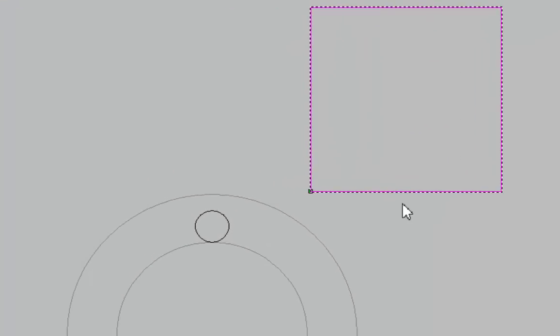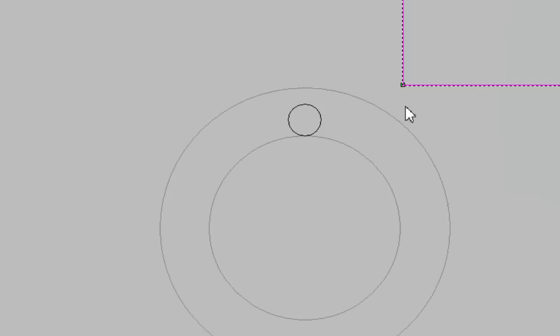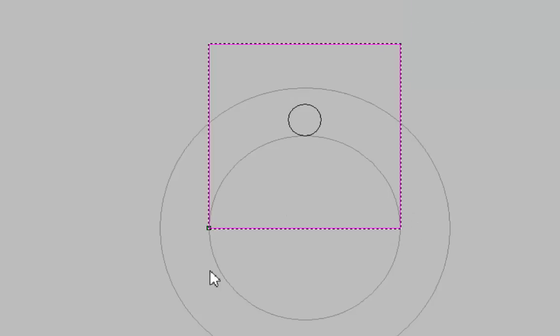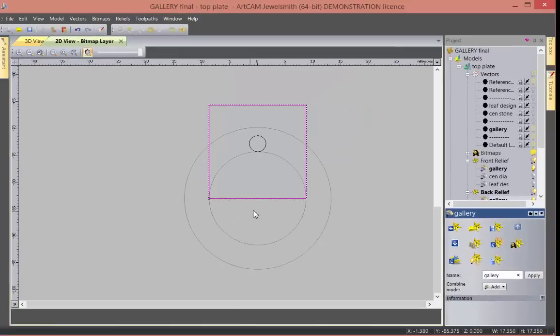I'm going to snap this. Watch this. Grabbing it on the snapping point or even on the edge, I'm going to snap this right here onto the center line. So drag that on its snapping point. Watch the cursor. It gets to snapping points. Drag it right over to the edge and it's snapped right onto the center of that line.